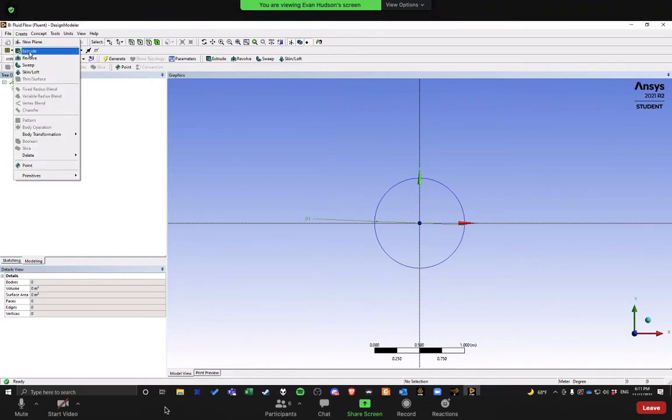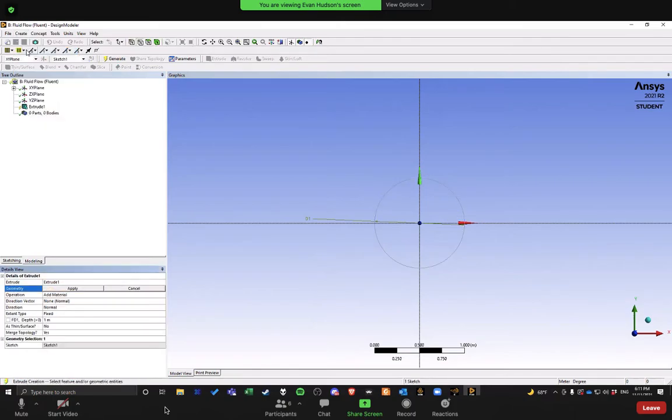This right here, and create, extrude. If you don't see it there, you can see create and extrude. And then I'm going to, well, actually, I had to click that first, and then I click the body next, like that. And then it says geometry. It's been highlighted. Make sure this is also blue. Click apply.